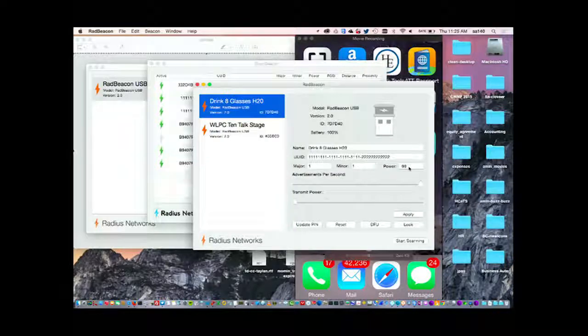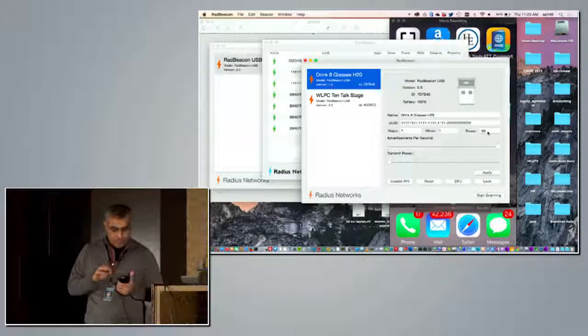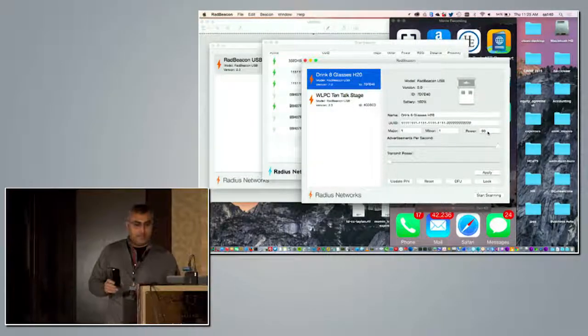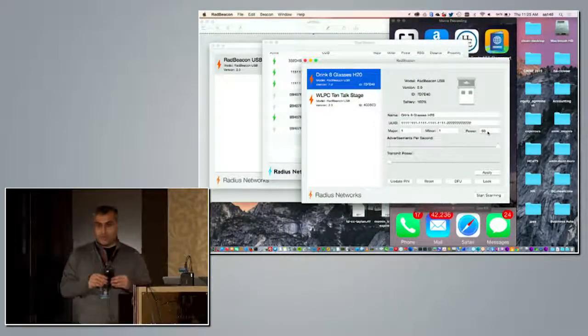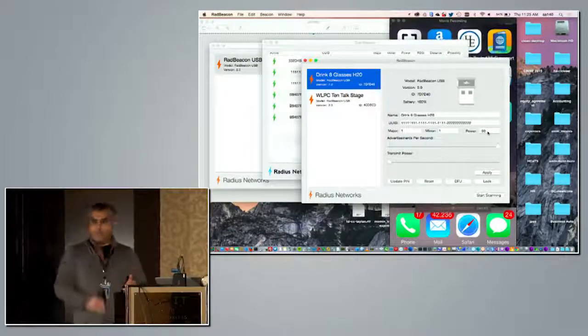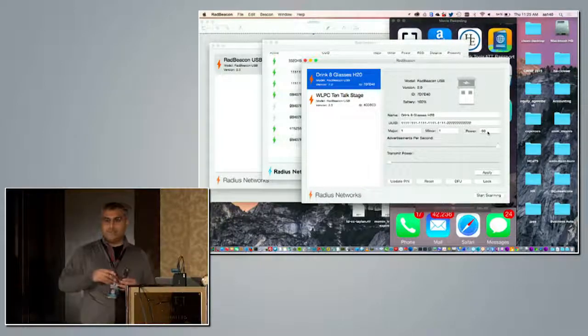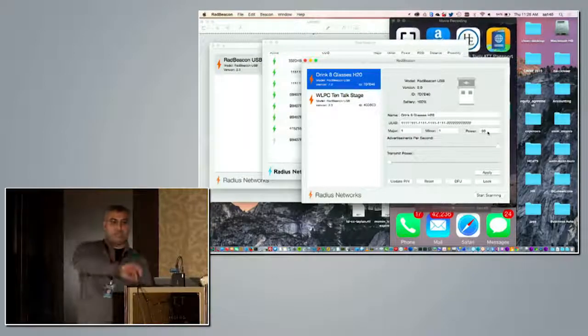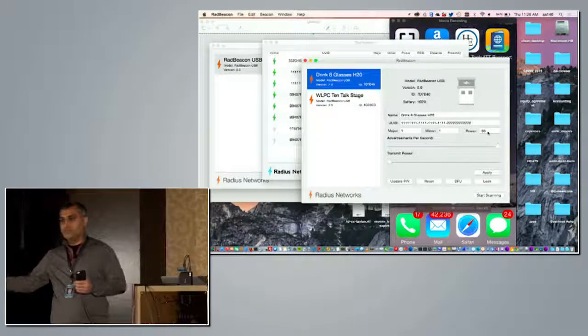in the beacon world, at least the iBeacon world, Apple says that you need to calibrate the distance from the beacon 1 meter away, and you don't take the cover off the 5S or the 5. One meter away, move the phone up and down for 10 seconds, and then that will calibrate the distance of the power 1 meter away from the beacon, and then that value is transmitted with the beacon to the actual receiver, the